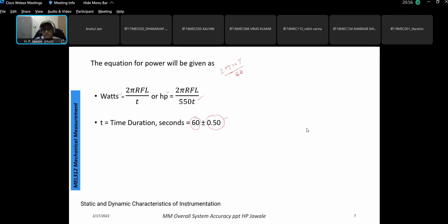Say, for example, you have started the motor and then you suddenly started the stopwatch. When you are going to end the experiment, you have stopped the machine and then you have stopped the stopwatch at the still condition to take the measurement. Now there is a time lapse between starting and stopping of the watch, taking the measurement, taking the proper reading, and so on. So because of the lag, there can be some error in the measurement of time.